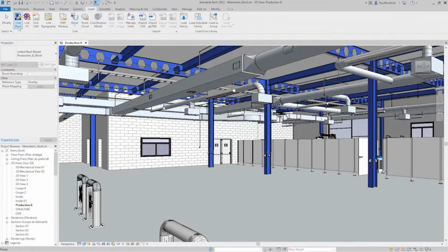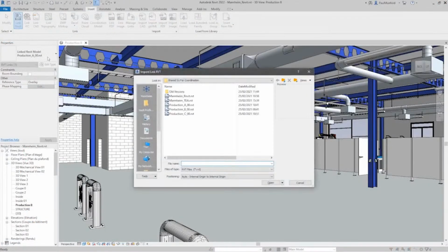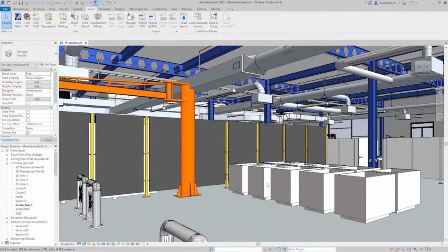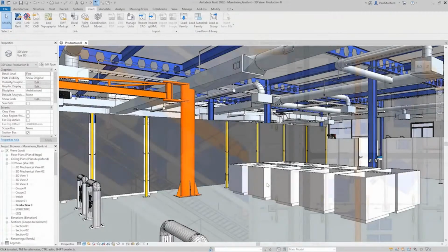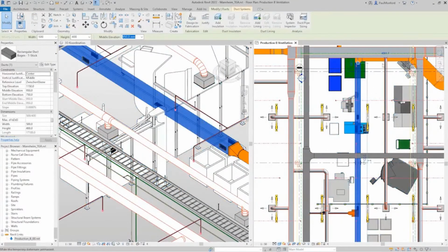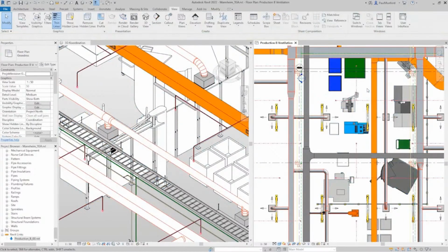Inside Revit, we can link in the project file we created with Inventor. Unlike Revit families, which represent individual components, our project file is placed using the coordinate system that we've shared between Revit and Inventor. This guarantees that our model will be in the right location for collaboration and review. The impact of the Inventor model on the Revit design can now be assessed and necessary adjustments made.